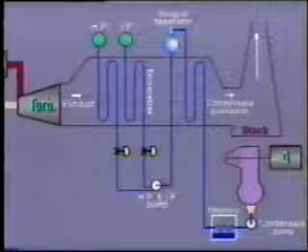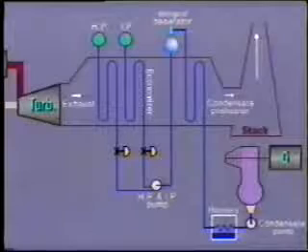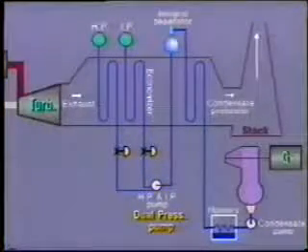As we saw in the last segment, where an integral de-aerator is used, an LP feed pump is not required. The condensate pump itself provides this service. Some installations utilize the same feed pump to provide feed water for both the HP and IP sections. In this arrangement, the feed pump is usually a dual pressure pump, with IP feed water being tapped off at an intermediate point. Of course, both pressure systems still retain their independent feed water control valves.